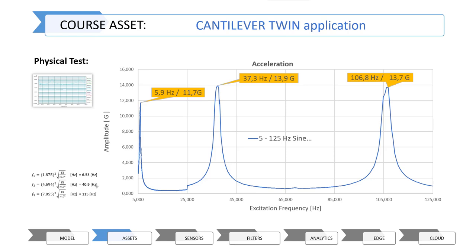And it could be that I didn't model the material properties correctly, but more likely in this example I didn't clamp the beam good enough. So the clamping was not infinitely stiff as presumed when you do the analytical calculations.